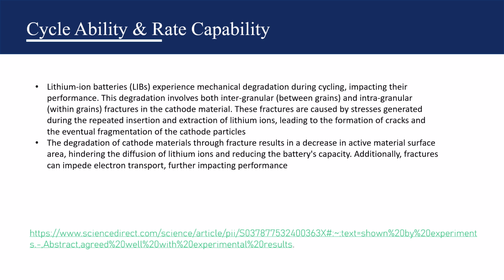Lithium-ion batteries experience mechanical degradation during cycling, impacting their performance. This degradation involves both intergranular, which means between grains, and intragranular, within grains, fractures in the cathode materials. These fractures are caused by stresses generated during the repeated insertion and extraction of lithium ions, leading to the formation of cracks and the eventual fragmentation of the cathode particles.